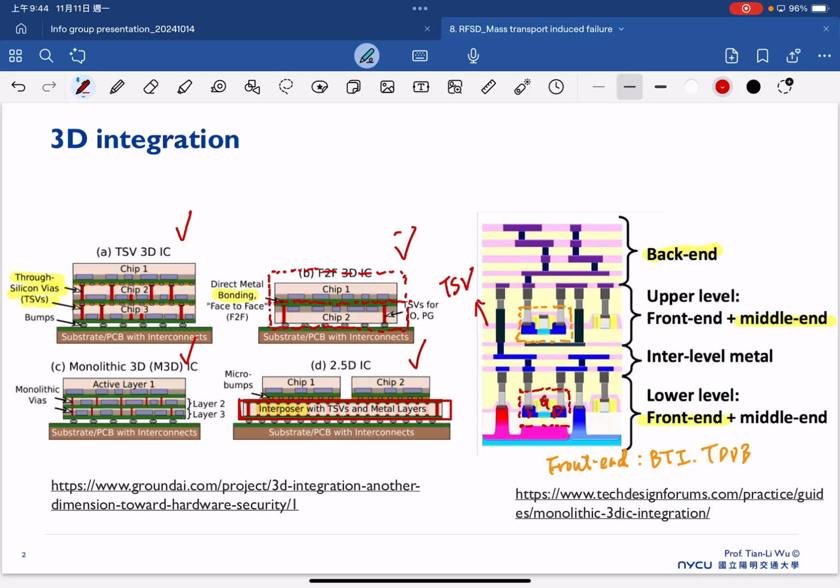So now if we look at the back end, the back end is mainly the group of interconnection lines in the last part of our chip, to connect the signal to the outside. That's what we generally call the back end. Inside the back end, actually there's no transistor. It's mainly a lot of interconnection lines and lots of passivation.